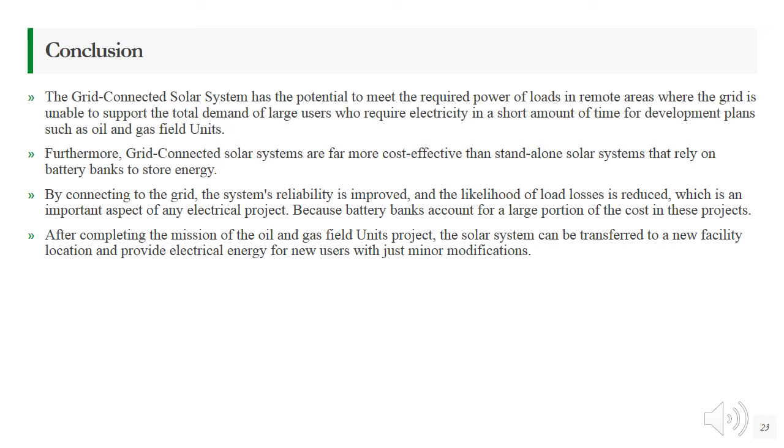Here we have the conclusion. The grid-connected solar system has the potential to meet the required power of loads in remote areas where the grid is unable to support the total demand of large users who require electricity in a short amount of time for development plans such as oil and gas field units. Furthermore, grid-connected solar systems are far more cost-effective than standalone solar systems that rely on a battery bank to store energy. By connecting to the grid, the system's reliability is improved and the likelihood of load losses is reduced.